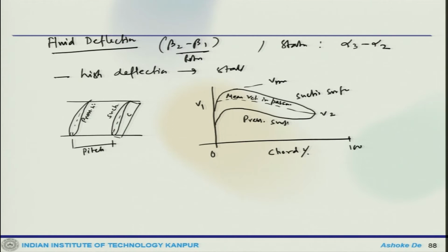So, what happens is that a constant axial velocity is assumed, then the relative angle is a measure of the magnitude of the relative velocities W1 and W2. So, the criterion which is called the diffusion factor or the DF was developed by NACA, which can be adopted here.